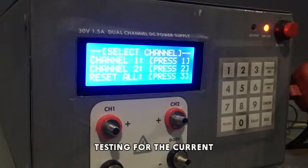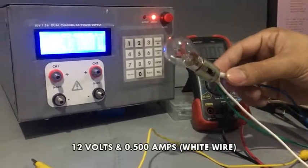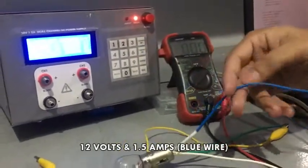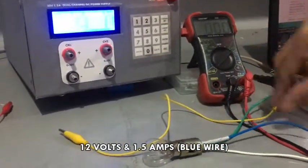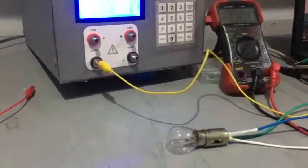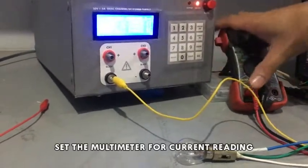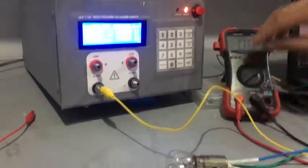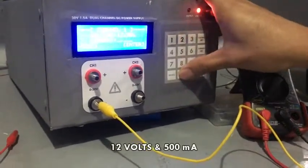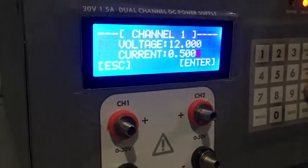To test for the current, I will use a DC light bulb with a current and voltage rating of 12 volts and 0.5 amperes for the white wire and 12 volts 1.5 amperes for the blue one. I will now connect the light bulb to the output terminal and I will change the configuration of the multimeter to amperes reading. I will set the voltage for channel 1 as 12 volts. The current is 0.5 amperes. I'll press OK.